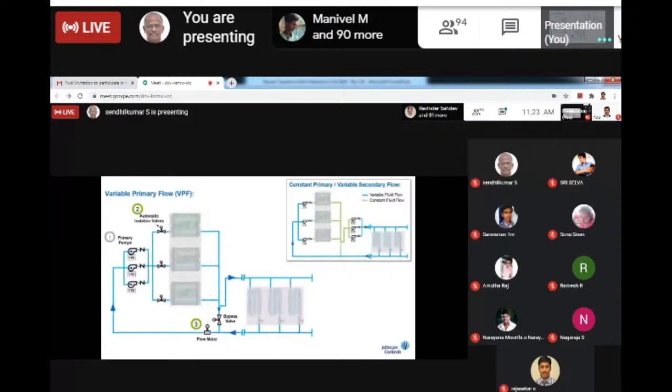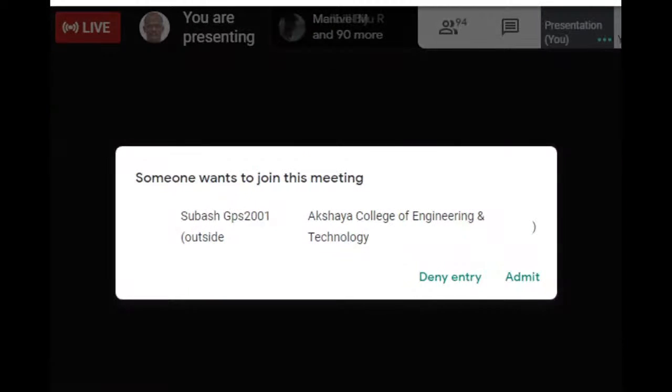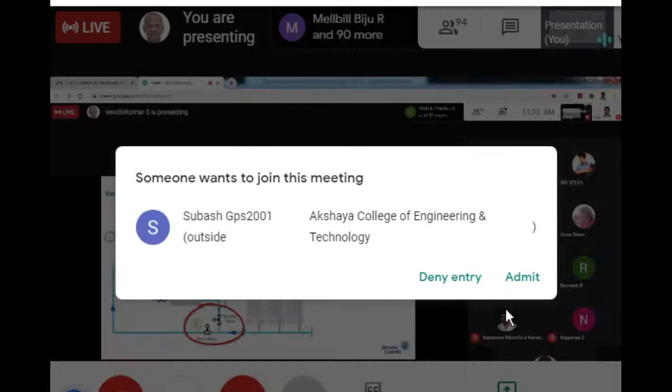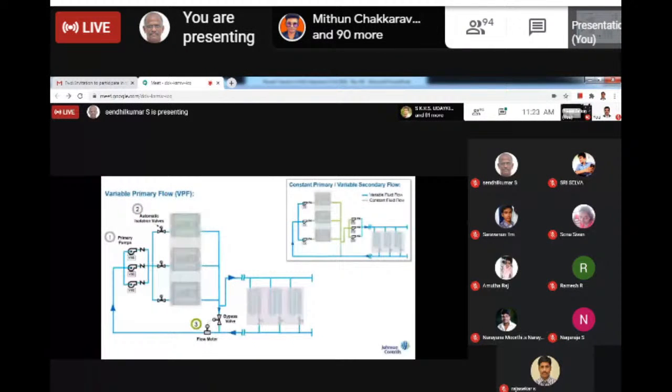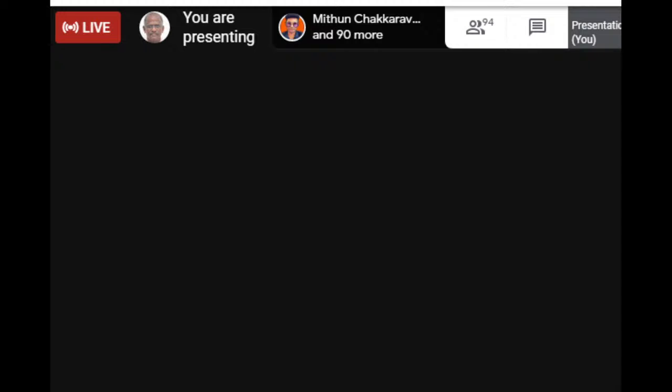And thirdly, we have our bypass valve and associated flow meter. The primary purpose of this duo is simply to maintain the required minimum flow rate through any operating chillers. In other words, based on the system load, the controls could tell the valve to open and allow fluid to bypass the coils to feed the chillers.